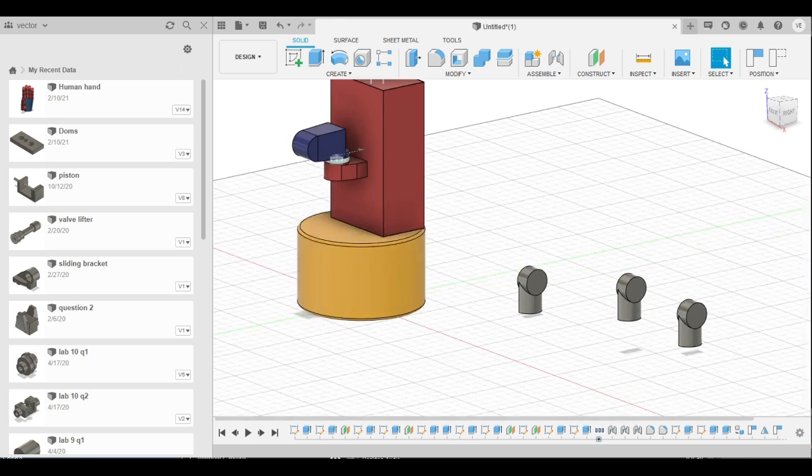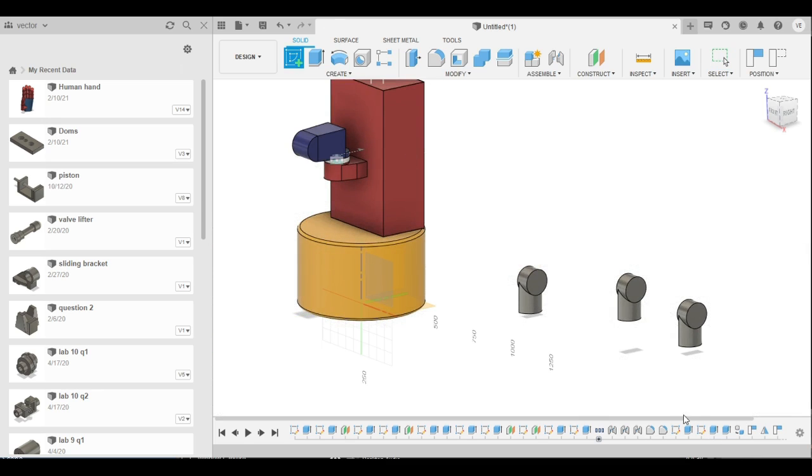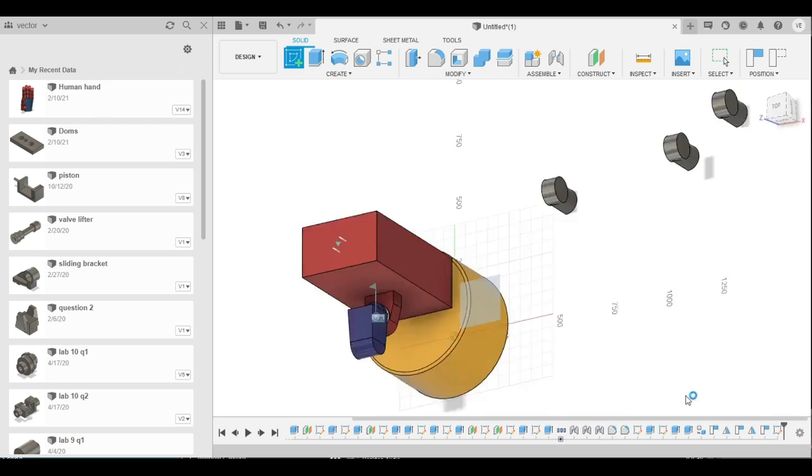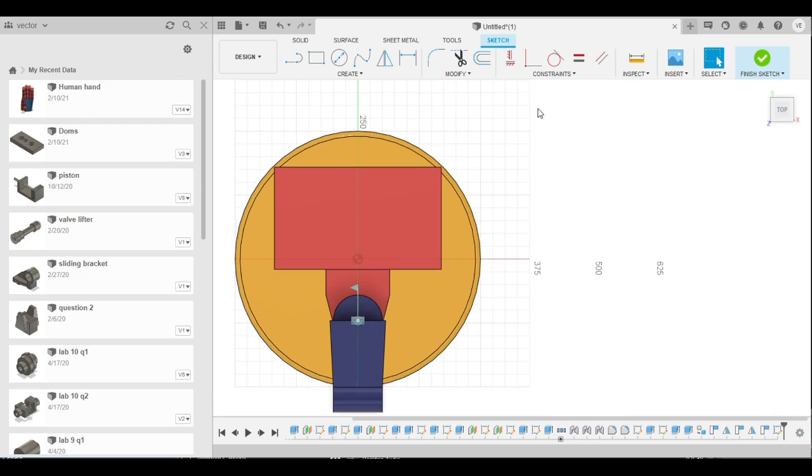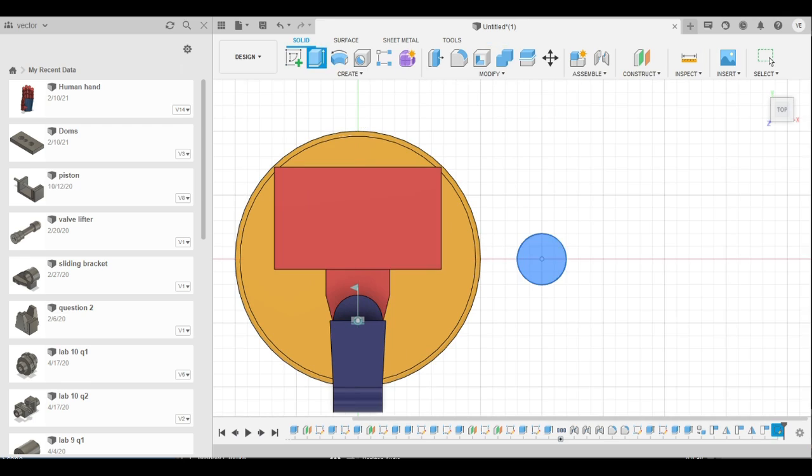We need two small cylindrical type of surfaces. So we'll again model them. It's of the same radius, and this time we have to extrude it by 20 mm. Oh, okay, we'll extrude by 30. It would be looking better, I feel.